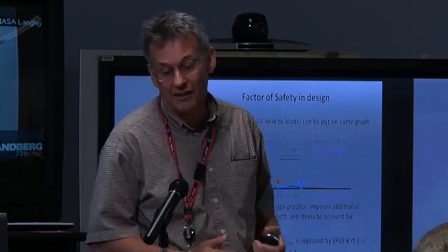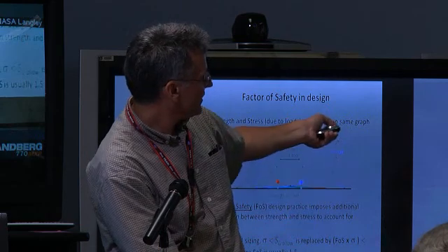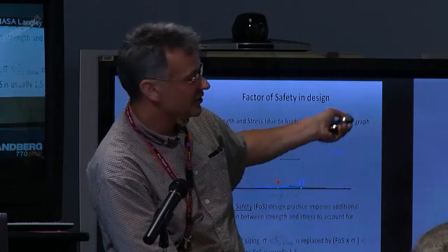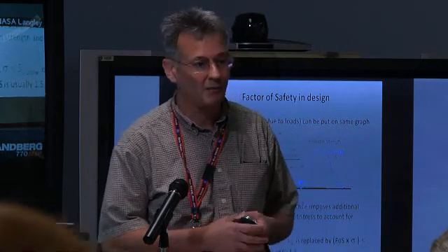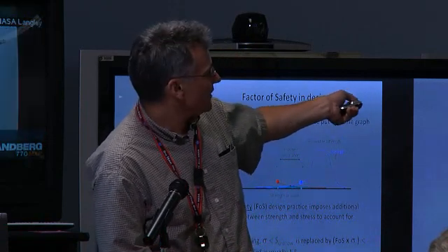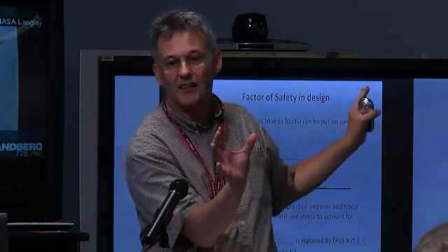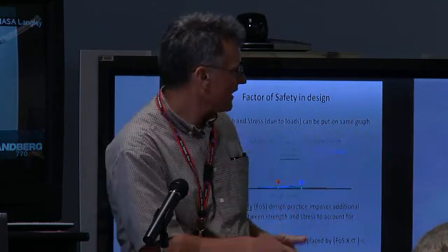Well, one way to minimize that area is just to make sure those two curves are further apart from each other. So basically, if you take the allowable strength, that's the 1 in 90, 1 in 100 times that it fails, and the extreme load, let's say it's a 1 in 100 times we've gone beyond the load level that we care about, and we just separate them. We put a factor of safety between them. It imposes a separation, so basically they stay away from each other. This area gets smaller and smaller, and we become a safer and safer structure.